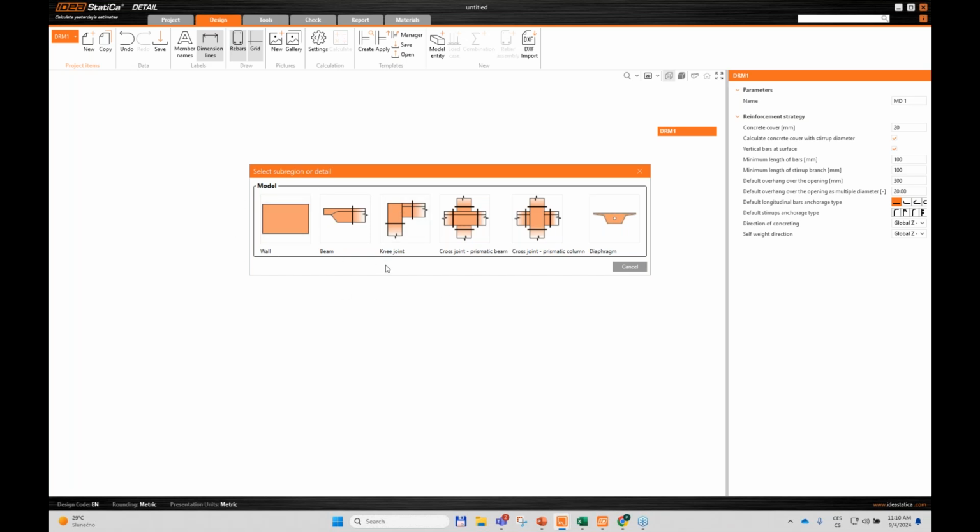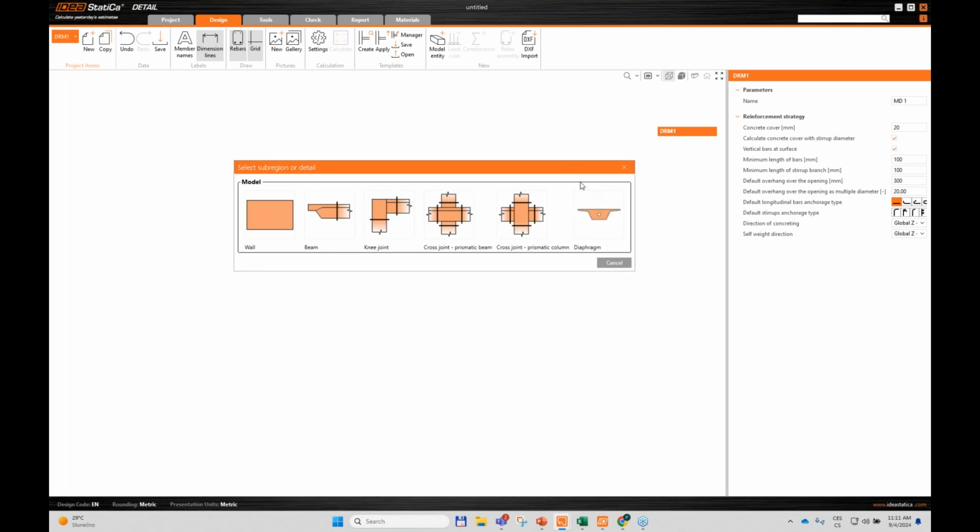The concrete is always represented by 2D elements, and the beam entity only has some better options how to input, for example, stirrups or internal forces when you have a part of the structure. But in general, you can create anything you wish, and it will always be the same finite element model at the end.